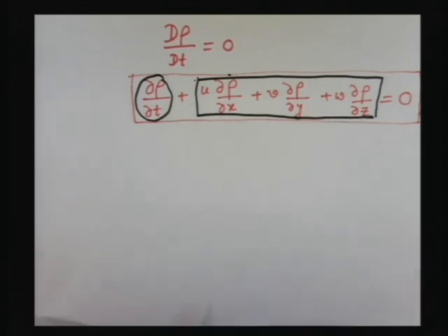This is known as variable density incompressible flow. I will give you a physical example. Many times we talk in terms of mathematics and it is not possible to perceive it from a physical point of view. So let us take a physical point of view. Let us say that there is a fluid in a control volume which is changing its phase. Okay. So let us say it is transforming from liquid to vapor or solid to liquid. Solid to liquid is of course not totally in fluid phase, but liquid to vapor is totally in fluid phase.